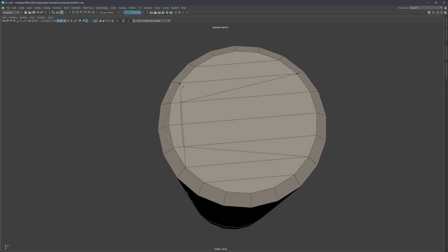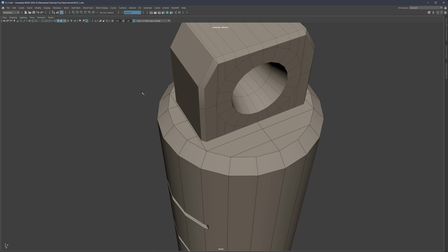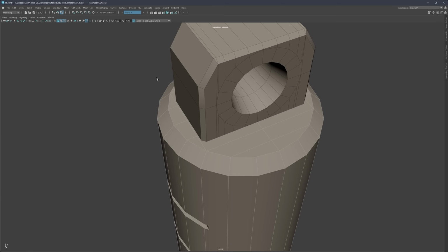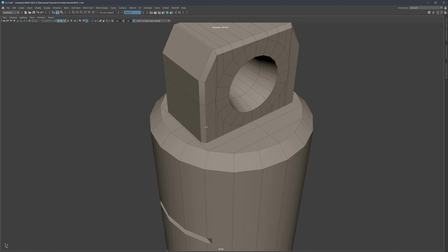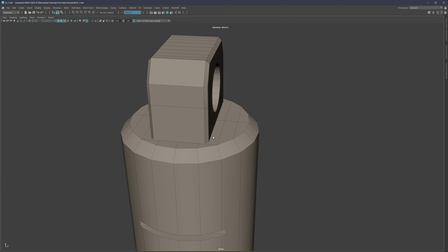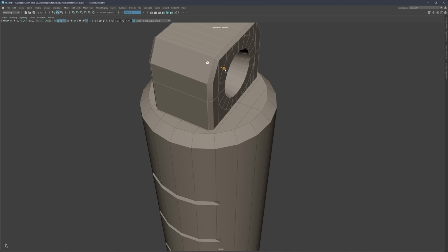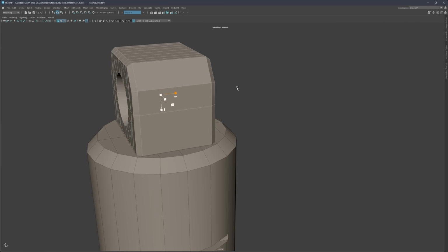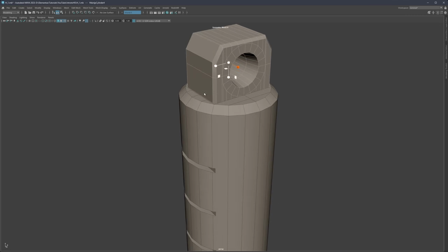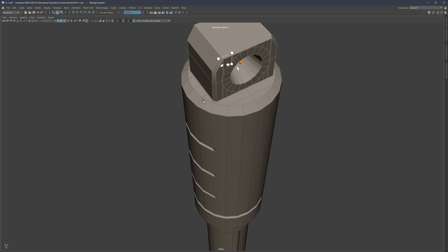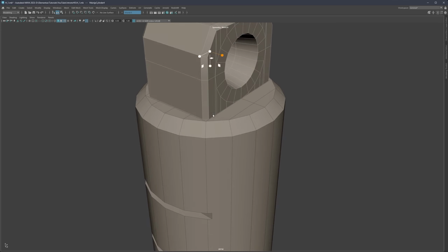Let me show you also one more thing. This result is happening simply because we are working with symmetry and Maya needs to have a middle loop. So let's establish a middle loop first, and then let's click here, and then right click to confirm. Control 1 to exit isolation mode, Q to confirm, go to object mode. And then we can see the situation where we are. So now we can either, let's say, leave the cylinder as is, or scale this a bit more, so that we actually give ourselves enough room to start working from there. So this part is now solved.